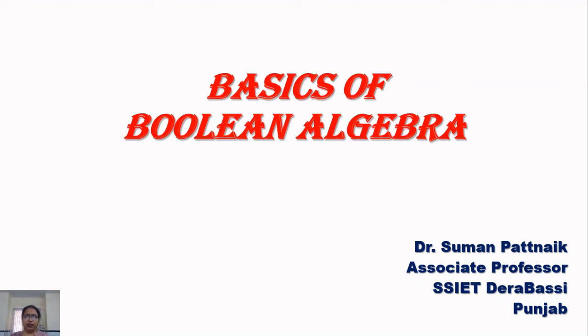Boolean algebra was developed in 1854 by George Boole, and it is different from ordinary algebra, but some theorems are similar to ordinary algebra. Boolean algebra is also different from the binary number system. In the binary number system 1 plus 1 is 10, but in Boolean algebra 1 plus 1 is taken as equal to 1, meaning one high is taken as high. So we are starting with some of the laws of Boolean algebra.